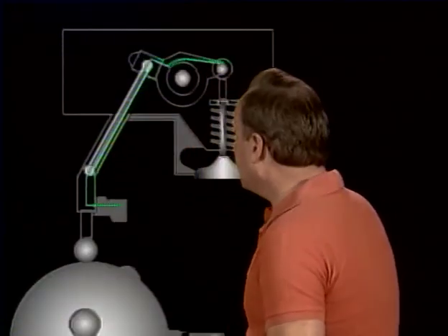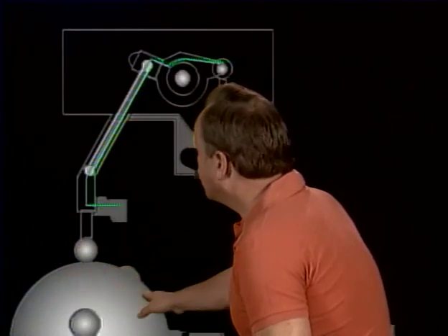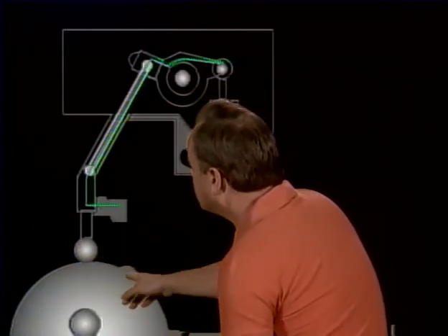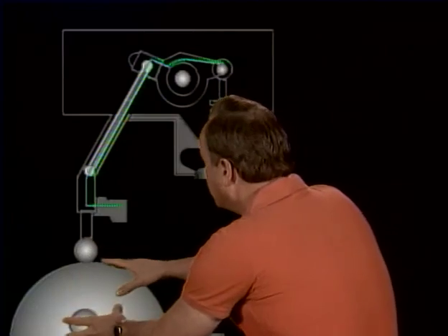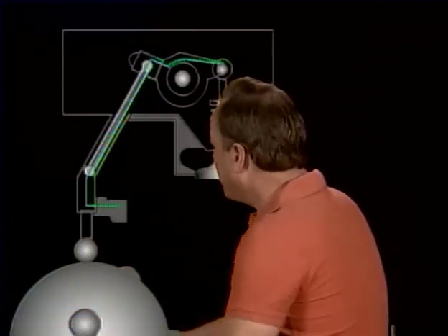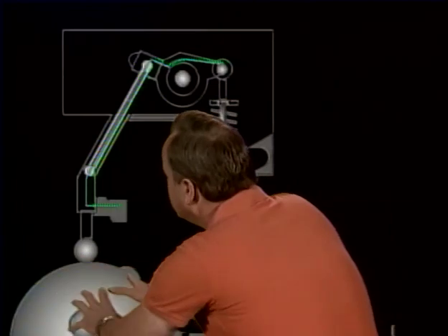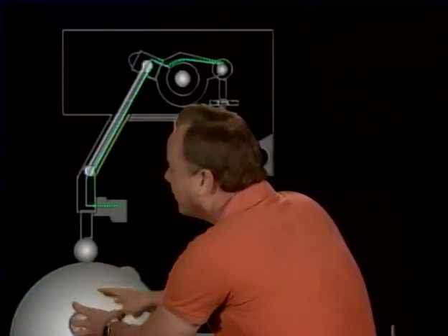Now, let you and I take a look at a radial engine. They love to ask you questions on the test about radial engines. So let you and I take a look at the cam ring on a radial engine. And here we have a cam ring on a radial engine. If you remember, this cam ring rotates around, and it's these lobes that push up the rocker arm and open the valve. Now, the thing that you need to know is that very often these cam rings are what is known as floating cam rings. By that, there is a lot of play, and these cam rings can float around on their bearing. It's amazing, but that's really the way it is.